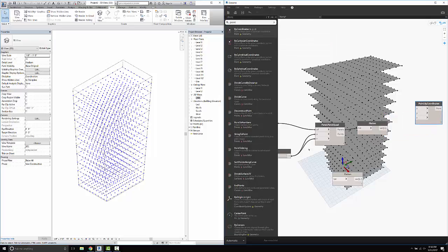and I'm going to make again some more sliders. So I'm just going to copy this one I've got and paste it 3 times. One for each of X, Y, and Z. And we'll plug those into this point component. If you don't put them in, the point just appears at the origin in your model. We're going to want to be able to control these later on, so that's why I'm going to go ahead and plug them in here.